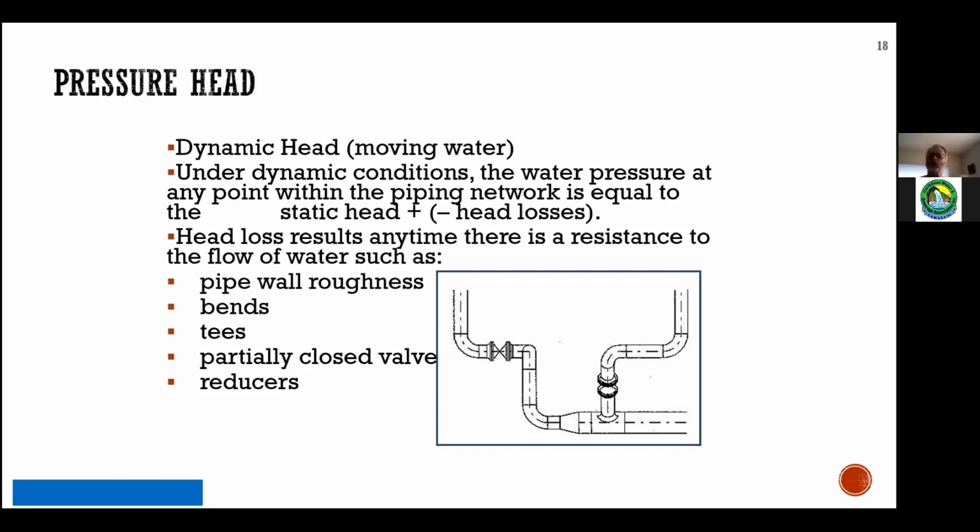Because if there's too much in the system through a combination of bends, old pipe, corroded pipe, perhaps valves that have been exercised and not reopened properly, we end up starving the system of energy.